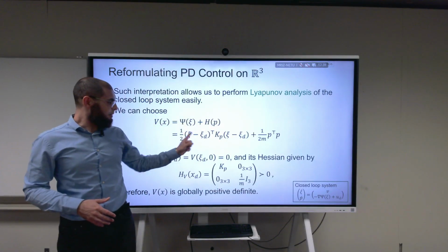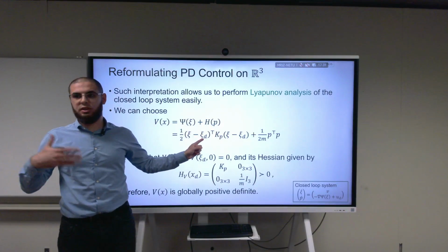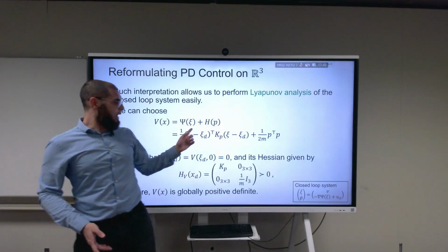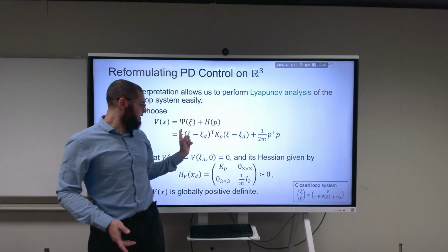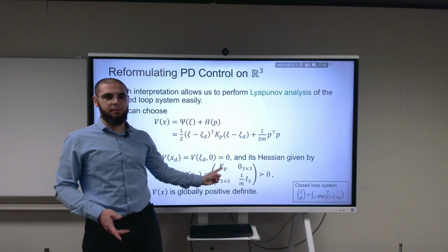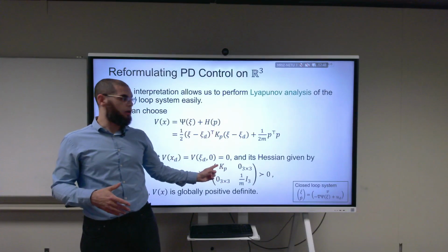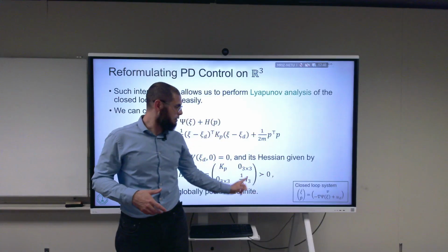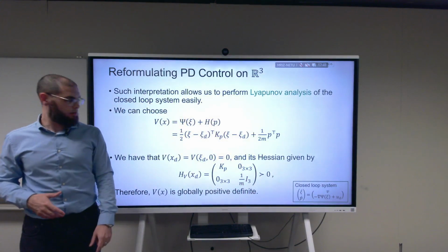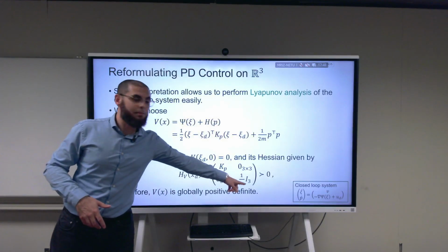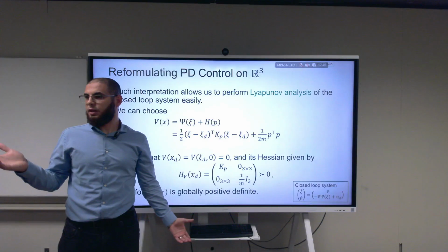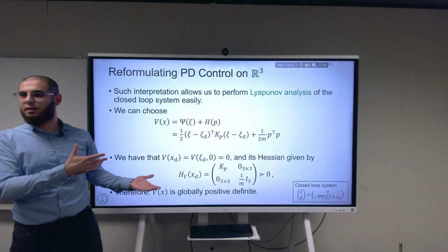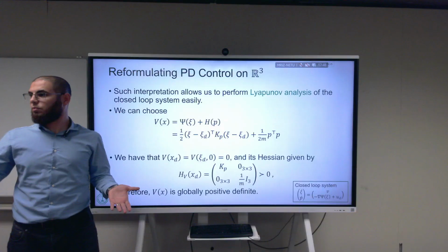Here psi d is a constant, just some number. So when I differentiate twice, it disappears from the equation. Then I have psi, and you see I have half Kp psi squared, something like that. So this is why the Kp appears here alone. This is very similar to what we did earlier. With the quadratic Lyapunov function, the kinetic energy gives me 1 over m multiplied by the identity, which is positive definite by nature. It's just the identity. And the Kp you design. Remember what we said, we choose the Kp to be positive.